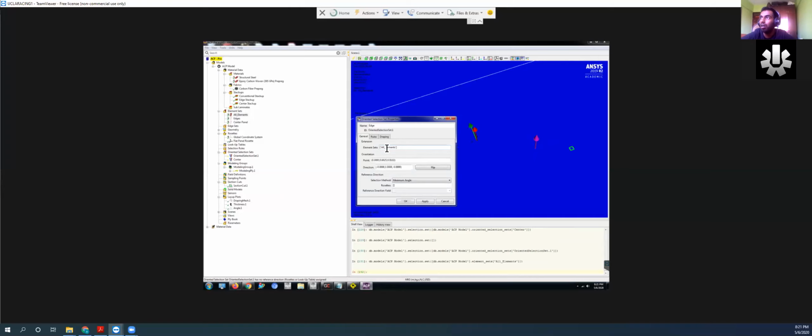All right. So in this case, I'm going to get rid of this. And then I'm going to click on edge. And then for the rosette, panel rosette. So in this case, I can see that it's okay. The purple pointing up, correct.